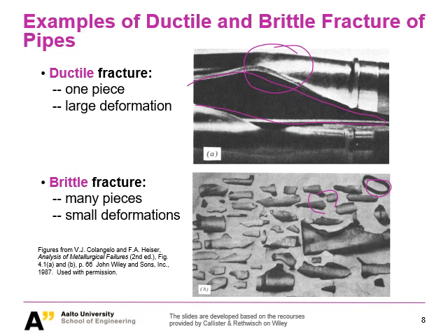And of course, the second feature you could notice is each piece doesn't really have large deformation, they have very small deformation. This is the very significant feature for brittle fracture.